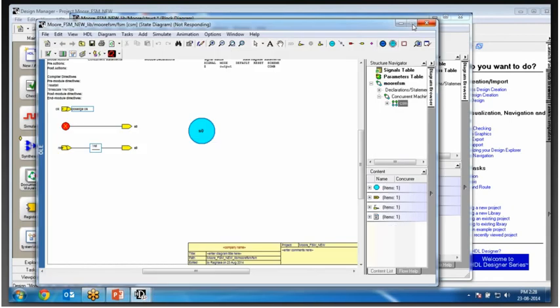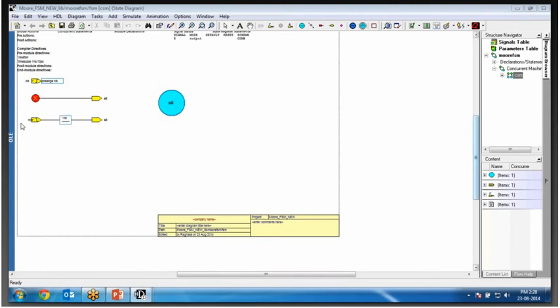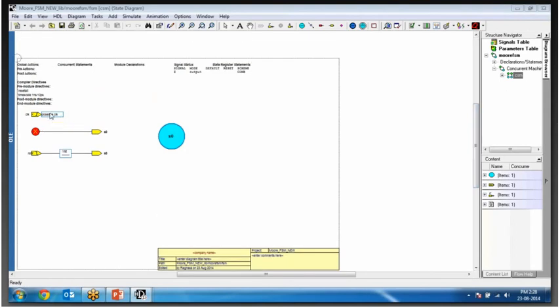If we are observing carefully, what we can find is clock, that is positive edge of the clock. So whenever positive edge of the clock occurs or any event occurs, it is with respect to the edge of the clock. And how is it dealing with state 0? If you are having any undefined state, your FSM will reset and go back to state 0. And you have an active low reset and it will be reset to state 0 again. For my Mealy FSM, I need to have 4 states: state 0, state 1, state 2, as well as state 3. I have my 4 states now.